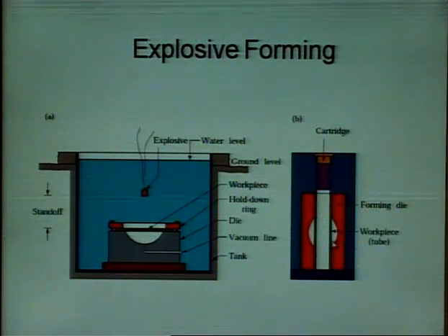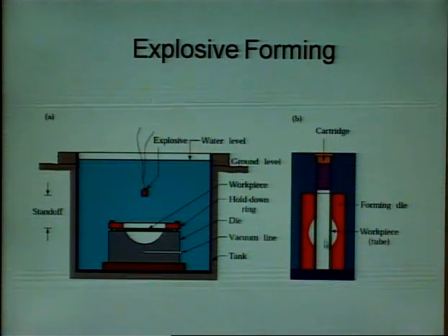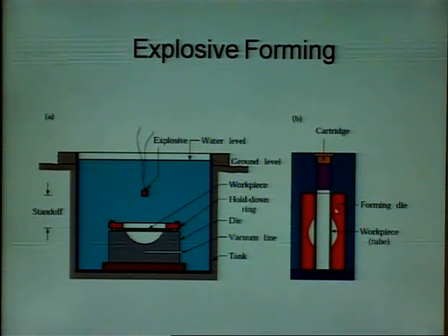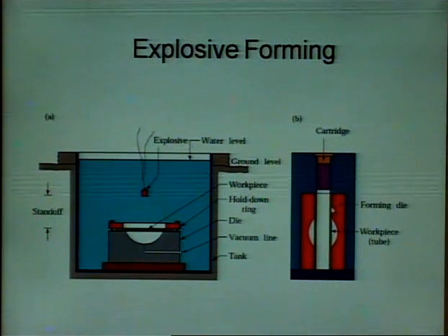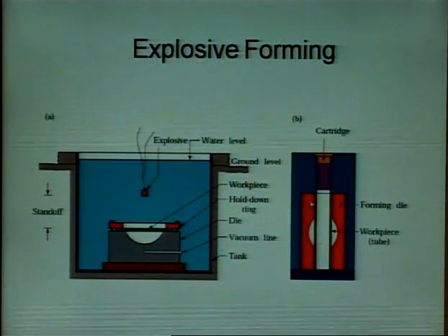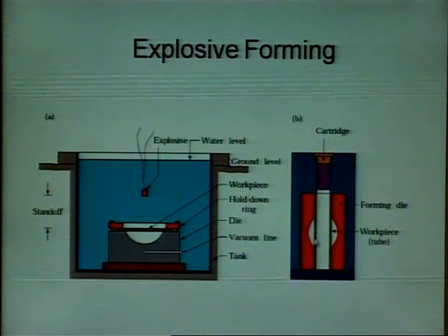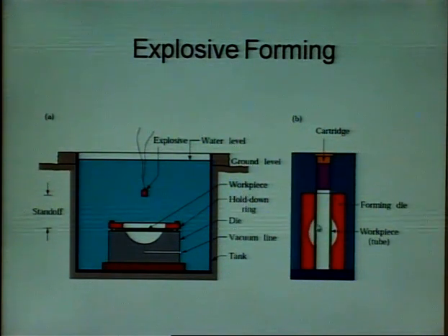It can go into this direction. So, when you fire this, when you generate pressure in this, nothing will happen here because this is constrained here. There is no space for this tube to go in this direction or in this direction, but it can always go in this direction, it can always expand here. So, you will get the desired shape here.